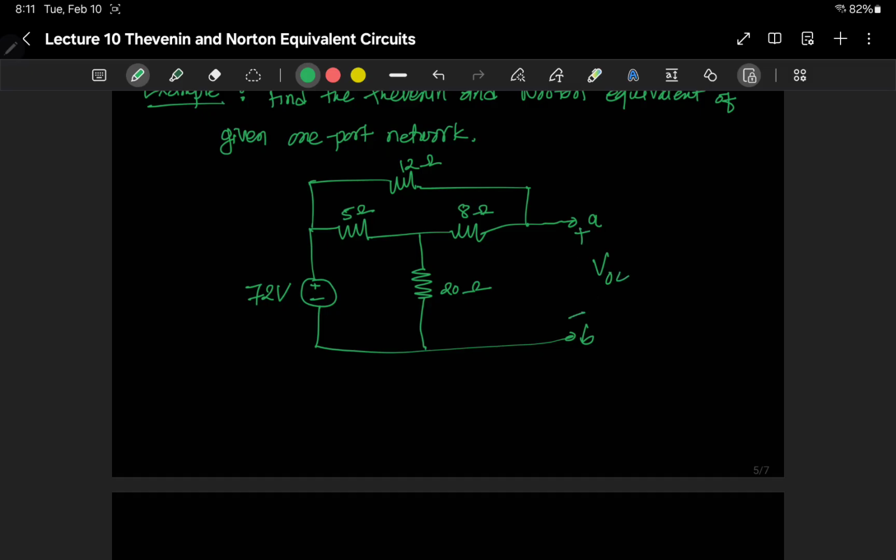Say this is the open circuit voltage, using other methods we have discussed so far, and one of the easiest methods will be node voltage. We discussed different methods, right? Node voltage and node current are two of them, and I mentioned the steps to determine which one to use. Between node voltage and node current, our idea is to pick the one with the lower number of unknowns, right? So let's check for that. Actually, this will be good practice.